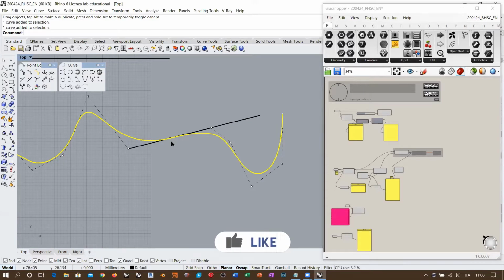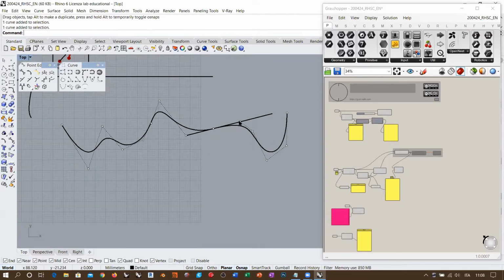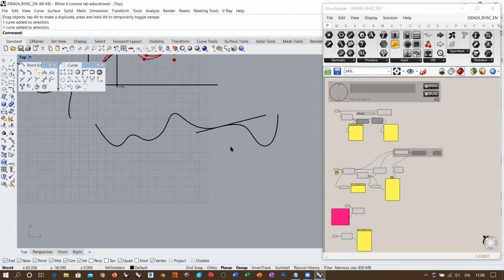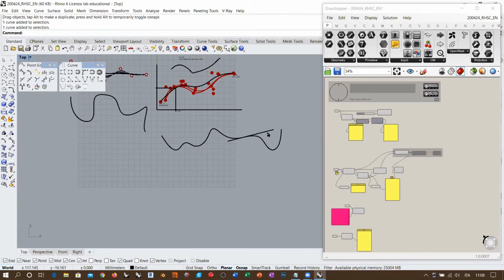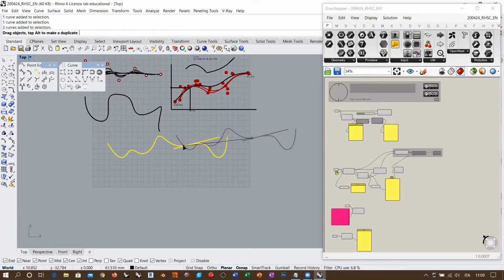which defines the initial and final tangent for a curve, is already useful to create a visible continuity between two different parts. This works both with curves and surfaces, as we will see during this course. But it's very important to start understanding what you can do with control points. So I will leave the scheme like this, because it's the first level of control that we have on our geometry, on our NURBS geometry.